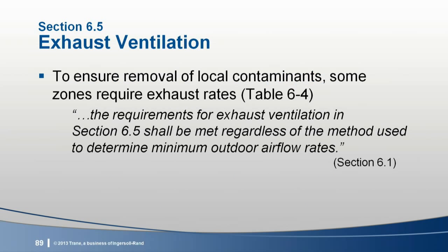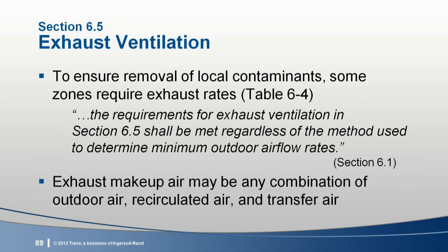Another nuance of this section is that the makeup air, that is the air that replaces the air being exhausted, can be comprised of outdoor air, recirculated air, or air transferred from another ventilation zone. This provides flexibility for the designer.